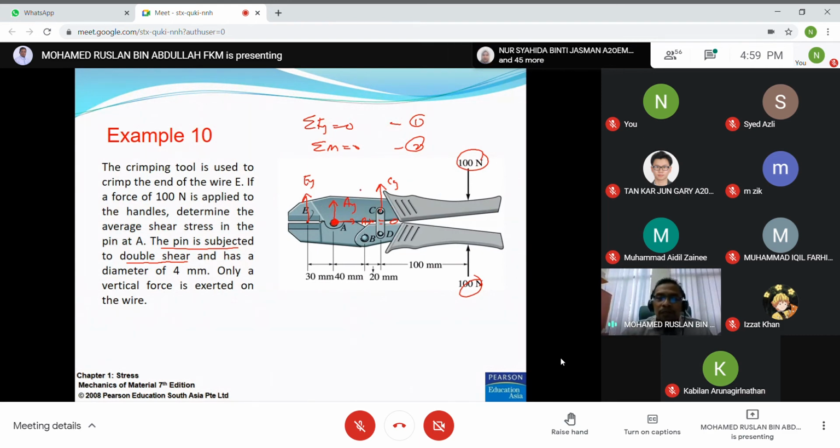So we go to the other alternative, this bottom part. Point D is a two-force member. Let's say this is DY in this direction, for example, and at pin B, let's say this is BY, and here is BX. From this diagram, how many unknowns do we have? 3: DY, BY, and BX.